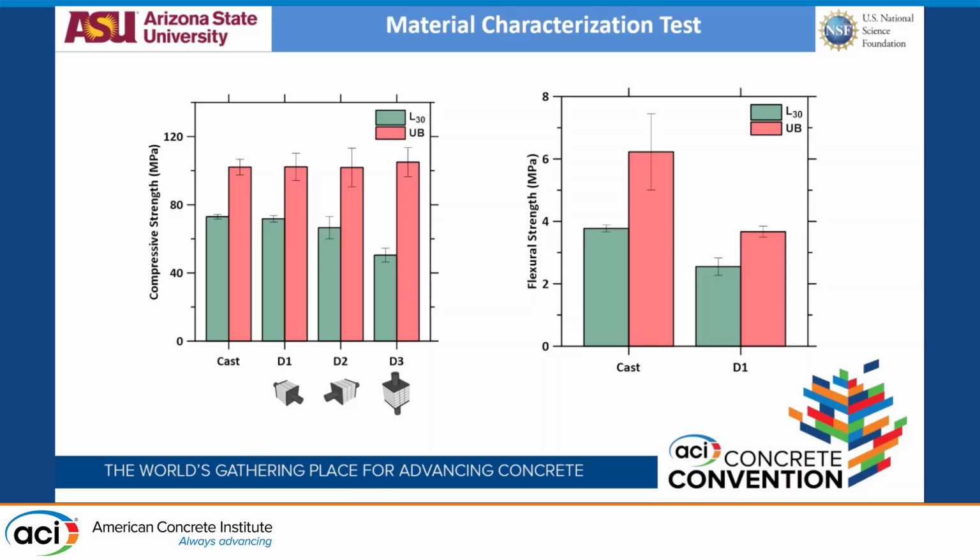There are different reasons for this. The first thing being the L30 mix, it's a slightly stiffer kind of mix with low SP percentage. So when you print it, because we are printing a slab, you are printing the filaments side by side with little to no pressure exerted in between, and the filaments become weaker. Sorry, I should have mentioned this before: the filaments are 10 mm height with 20 mm width, with a 20 mm nozzle.